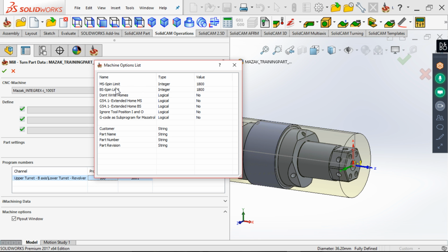Mostly the customer will never change this. It depends on the material of the part. It's the maximum constant surface speed, okay? It is used when the customer uses turning and clicks that he would like to make a constant surface speed. That's very nice. But what happens if the tool goes to X0? It means infinite speed, which the machine cannot perform.